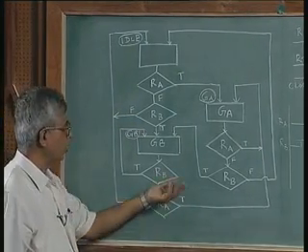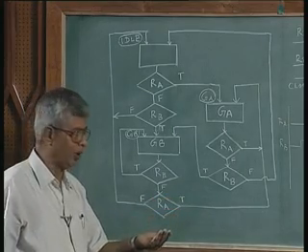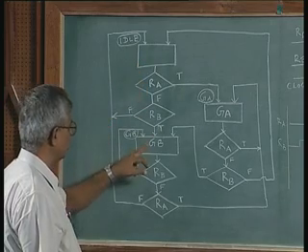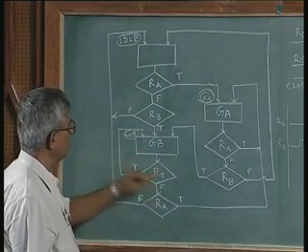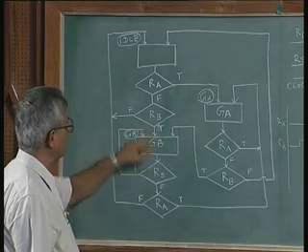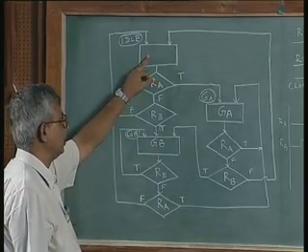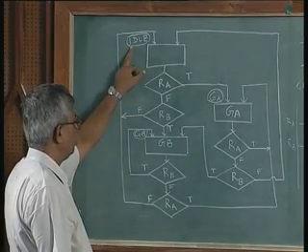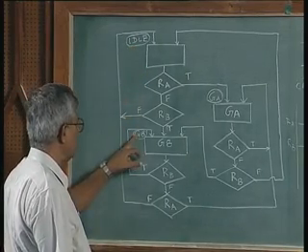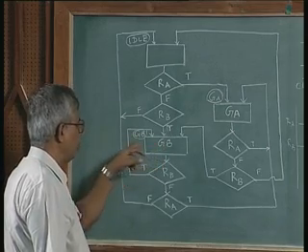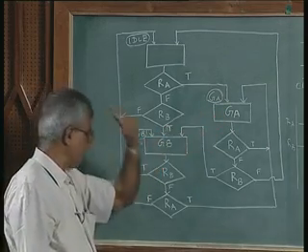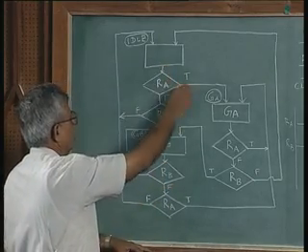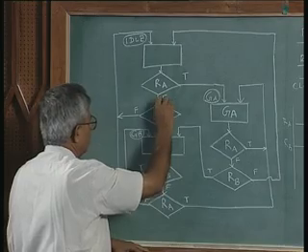I want to draw your attention to a couple of points here, which is more a convention than any concept or theory. The ASM is drawn like this, as I said, with rectangles and diamond boxes, and within them is the signal. Here there is no signal in the idle state, so there is nothing inside. What you have is the state name, the box name: idle state, GB grant B state, GA grant A state, and always an arrow. You always draw arrows. An arrow going to this, an arrow going out of this, two arrows should come out of this, like this.